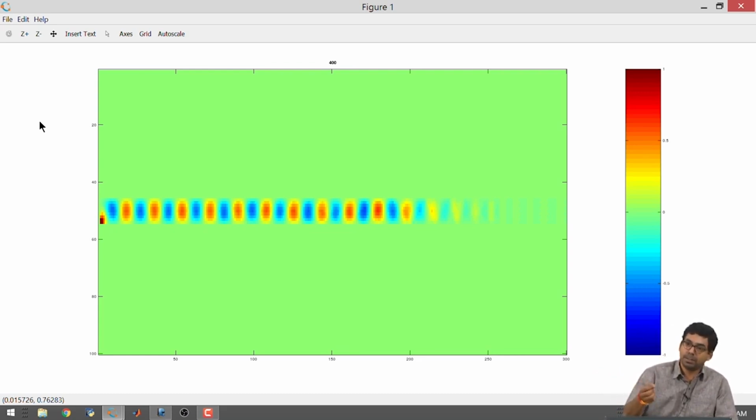Usually a point source gives out light in all directions, so you could use a point source to excite all the modes, but if you want to exaggerate the presence of these modes, then you can move it in the cross section of the waveguide. That will give you an exaggeration. But a truly single mode waveguide, no matter where you excite it, will eventually form a single mode pattern only. And in this case, it is just by adjusting the frequency that I was able to get this pattern.